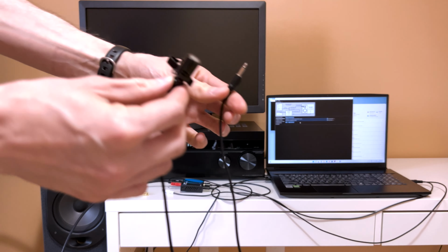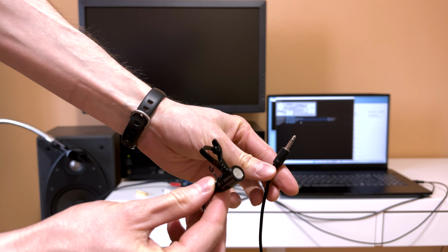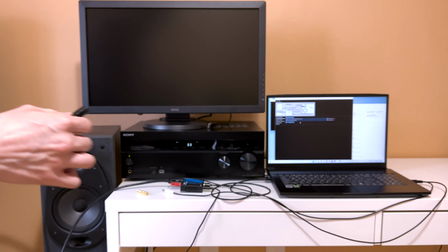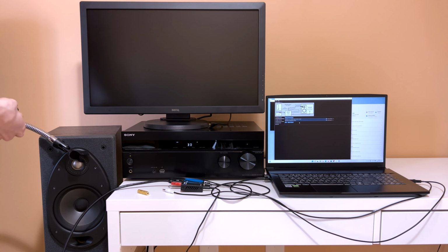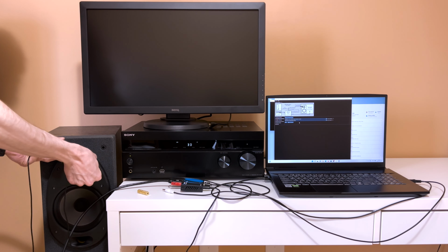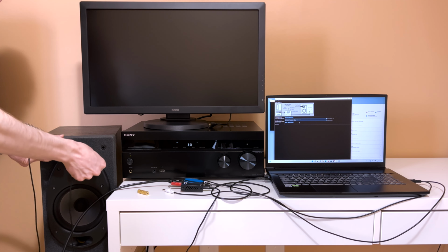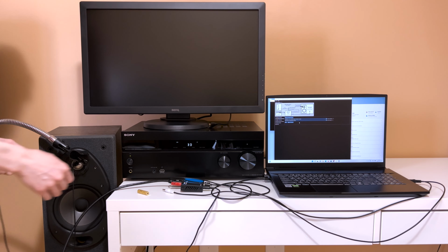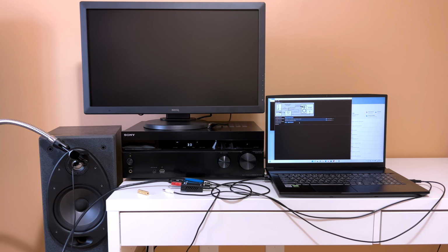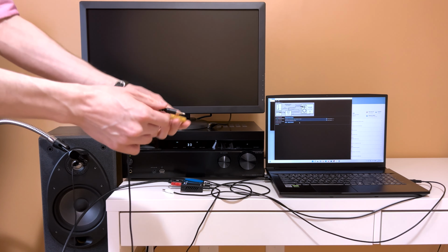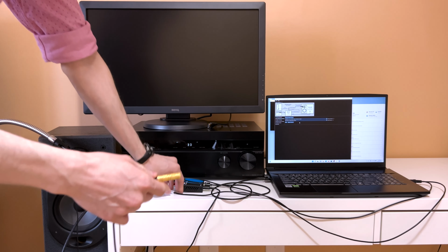Next, let's try using a microphone to measure audio latency of the speaker output of this receiver. When using a microphone, it should be positioned as close to the speaker as possible to measure the audio latency that is specific to the receiver. This is a different technique than calibration of a room setup, where you might want to include the time that it takes sound to travel to a specific listening location.